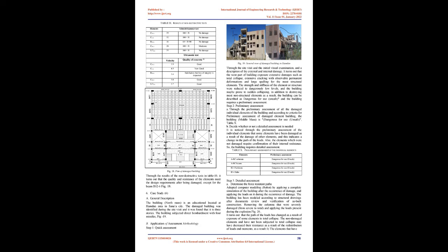Fig 17. It turns out that the path of the loads has changed as a result of exposure of some elements to total collapse. The non-damaged elements that have not been subjected to total collapse may have decreased their resistance as a result of the redistribution of loads and moments.